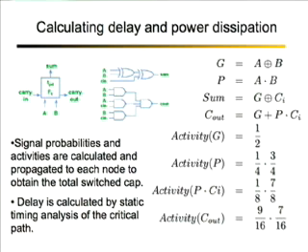And in order to find out the total switched capacitance, the average switched capacitance of a ripple carry adder, we have done a careful analysis of the probability of propagation and activation at each node. So without going into the details of the calculation, essentially what we are trying to do is that at each node we are trying to figure out what is the activity, because the total switching energy would essentially be the CV squared at that particular node multiplied by the activity at that node.